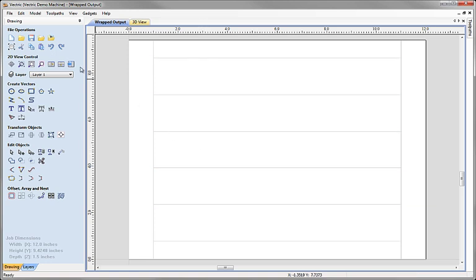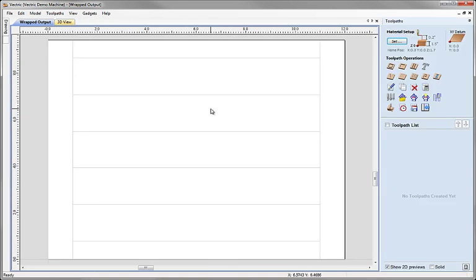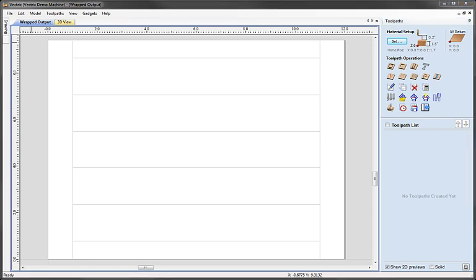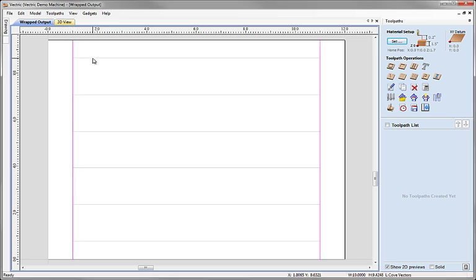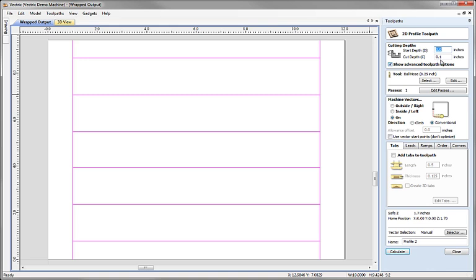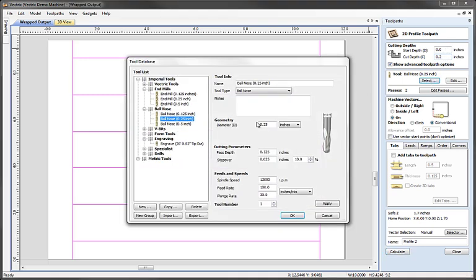And now we can go across to the toolpath tab and we can use these in order to calculate a different type of wrap toolpath. So in this case, let's take all of our lines. I'm going to click to select the 2 coves, click to select the lines for the flutes, come over to the profile toolpath, and all we want to do is just machine these flutes down, say, to a depth of 0.2 of an inch from the surface, and we're going to select a large ball nose tool. We're going to select a 1/2 inch ball nose tool to cut these flutes around the part.